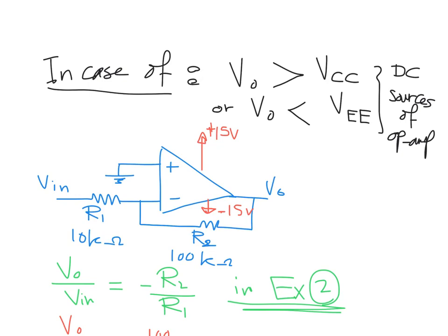If we have any voltage source connected to this operational amplifier, it implicitly means that VO, with any amplification factor we expect, can't exceed the maximum of this voltage source or go below the minus voltage source. So there is one main condition to take into account: VO can't be greater than VCC, or less than VEE.